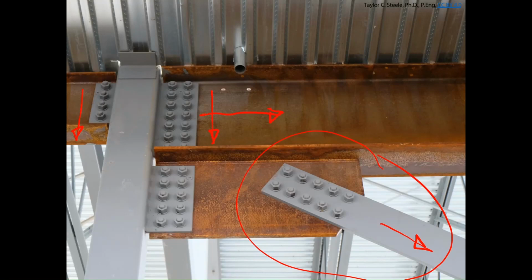There's no plate on the other side, and so are those bolts in single or double shear? Single shear. So there's only one shear plane that can develop here. We've got the gusset plate, we've got the tension member, we've got some bolts through it. There's only the one shear plane through which we can transfer that force from tension in the member to shear in the bolts. And similarly, on the other sides here, it's pretty much the same deal. Despite the fact that we might have perhaps two components of force here, we would still be transferring that force ultimately perpendicularly to the bolts, and so those bolts would be in shear and in single shear.